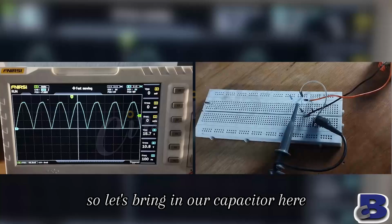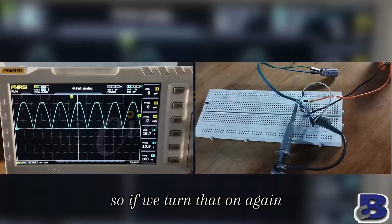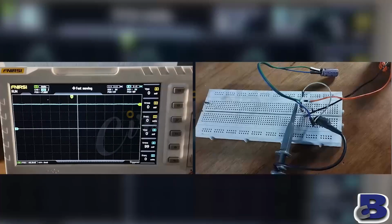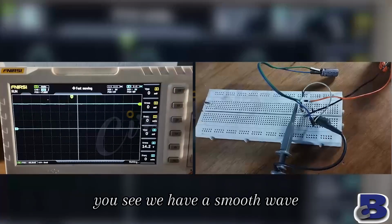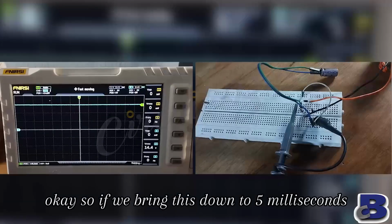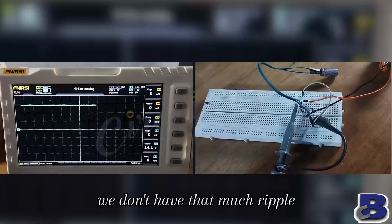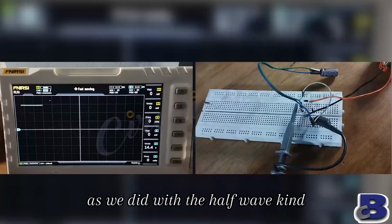So let's bring in our capacitor here, and let's see what the wave is going to be like. So if we turn that on again, you see we have a smooth wave. Okay, so if we bring this down to 5 milliseconds, like we did before, we can see we don't have that much ripple as we did with the half-wave kind.